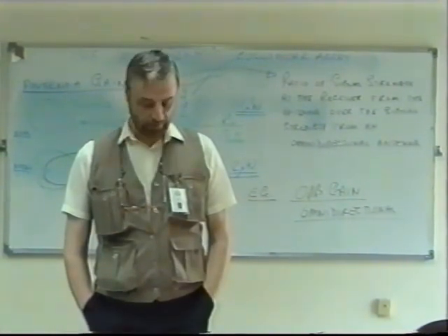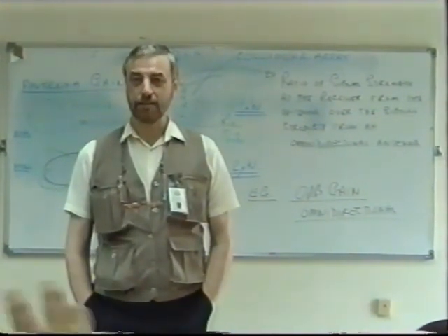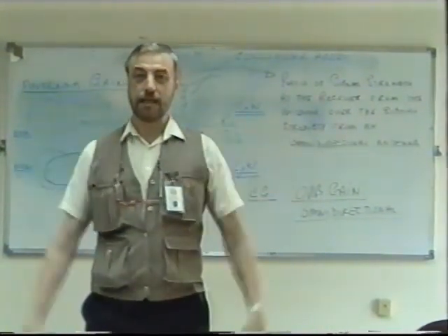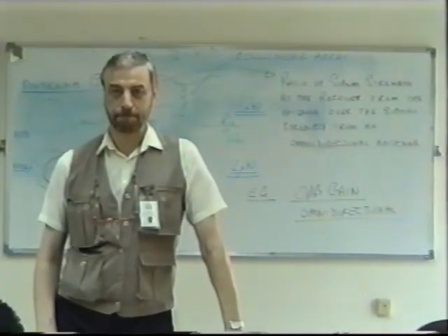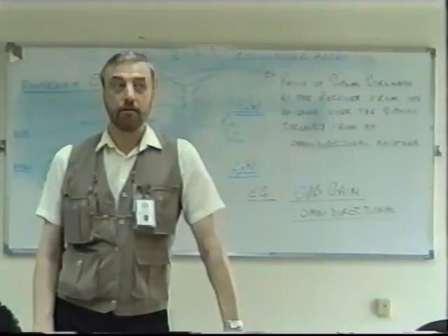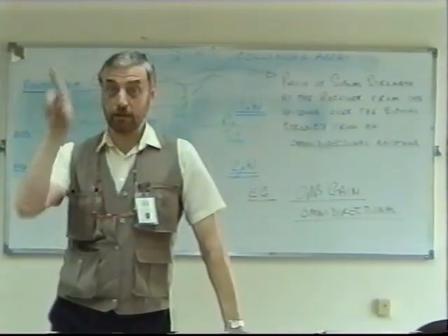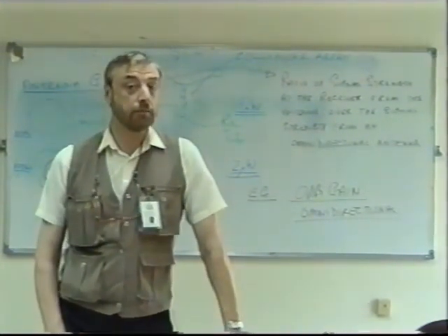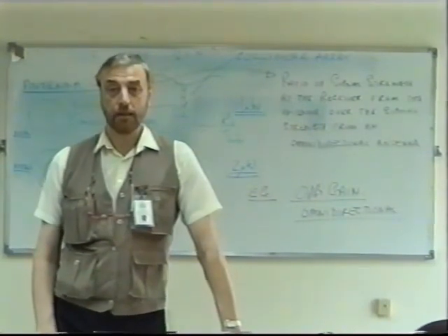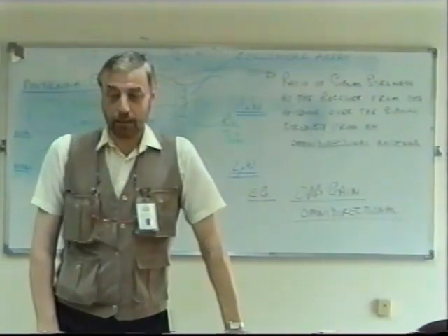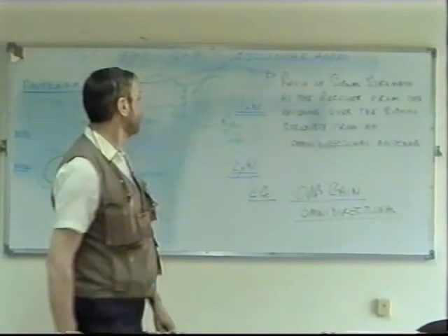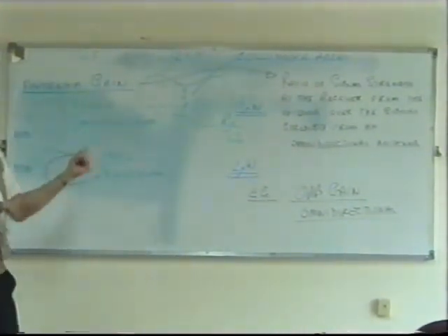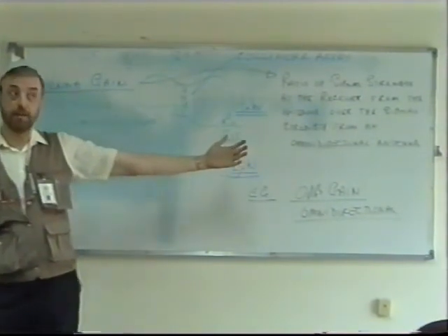Completely omni, yes. That is just like a balloon around your antenna, expanding. That's 0 dB gain. Anything else will have some other shape to the diagram. What is the advantage? You don't waste it. The plus 3, plus 6. Saving power, because instead of using a 200 watt transmitter, a 100 watt transmitter will do the same job if it's a 3 dB gain.